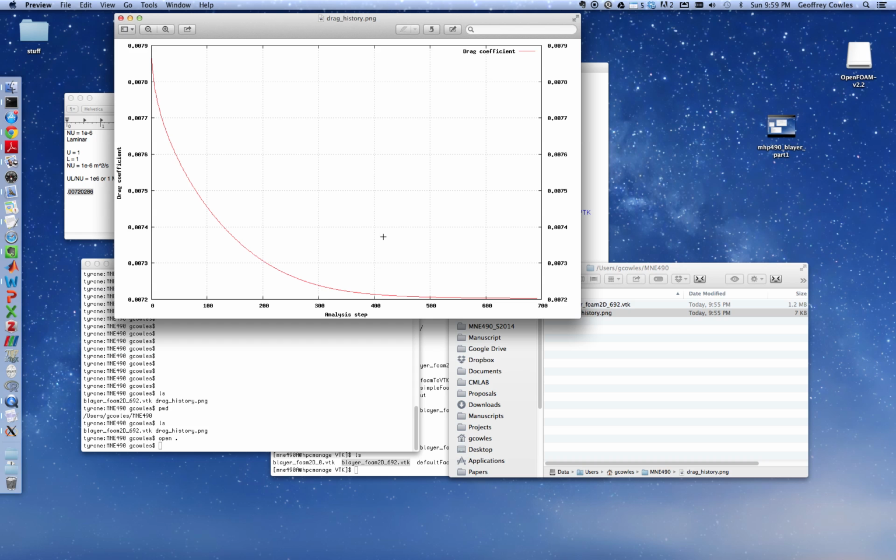Later, when we start working with airfoils, we're going to be using a steady state solver, and if the flow over the airfoil is not inherently steady state, which generally happens if the angle of attack is too high and it's starting to stall, then we're not using the right flow solver for that. We should be using a transient or unsteady flow solver, which is quite expensive. So we're sticking with steady state solutions. That flow solver will fail to find a steady state solution because there is not one.